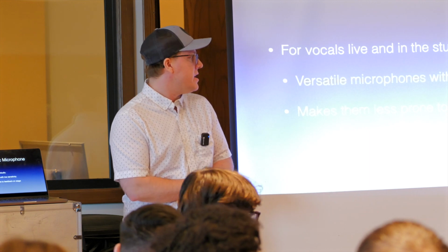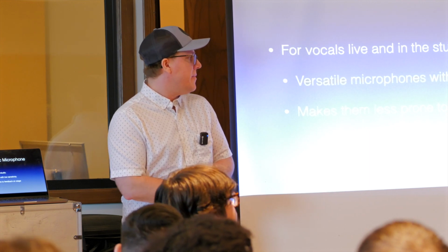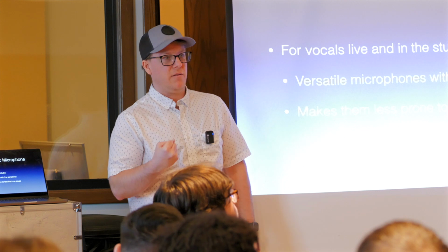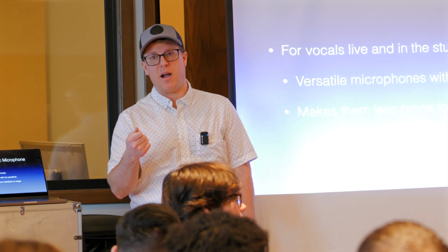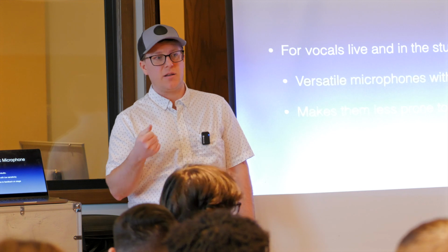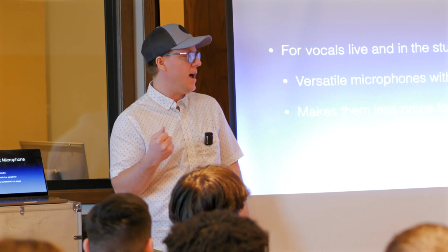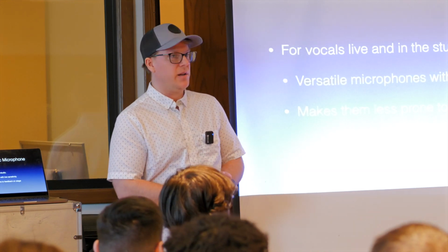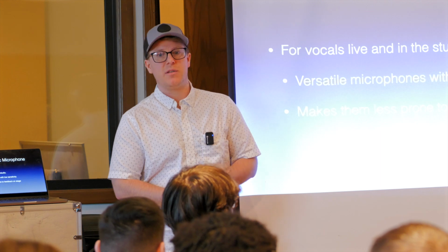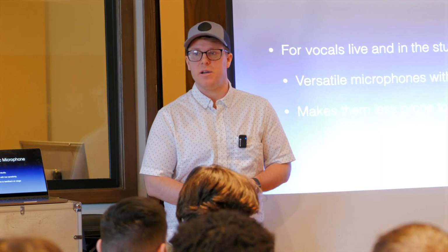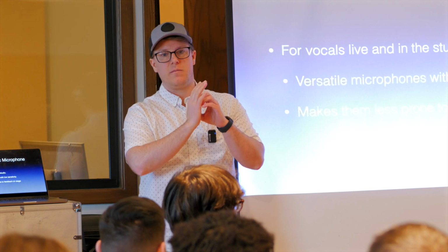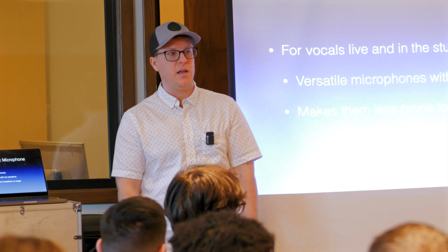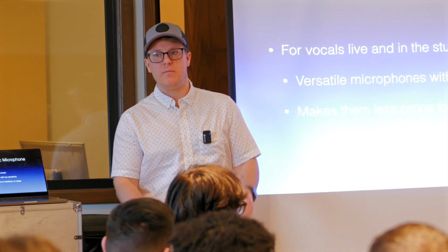They have low sensitivity, which makes them less prone to feedback on stage. So you can get a lot of gain, a lot of headroom on dynamic microphones before you start to hear any sort of feedback happening. I personally really like dynamic microphones. When I'm recording vocalists in the studio, I'll always pop a dynamic microphone next to the large diaphragm condenser or ribbon mic, just to kind of blend it in with the sound.